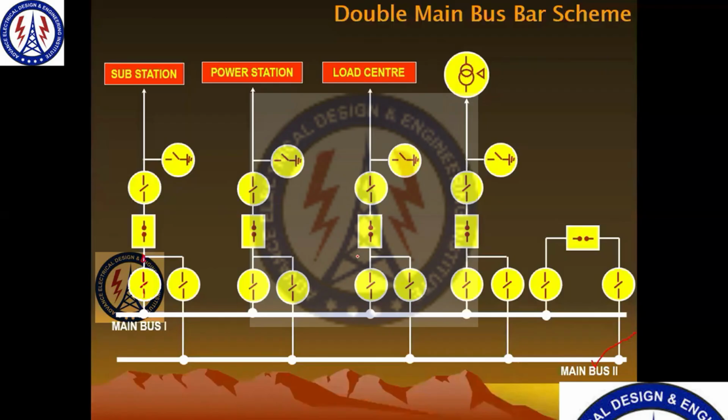So with this, you can see both the bus bar schemes are the same. Only the connection is different. Only the tapping of this isolator is different. Here we are doing it here, and in the previous one we are doing it before the line isolator, after the line isolator if you say from the downside. So this is the difference.